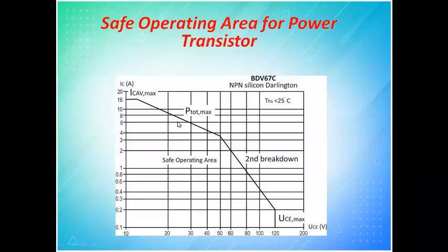So for a device there are two types of breakdown occurring. You have to identify this only from the data sheet. Take the data sheet and come to a conclusion that this transistor can be operated safely. If you want more current, then you have to reduce your voltage. Which current is this? This current is your load current. Load current purely depends upon the load. The current I have drawn here, IC, please remember, is nothing but load current. Load current is the current flowing across your emitter to collector to your load.